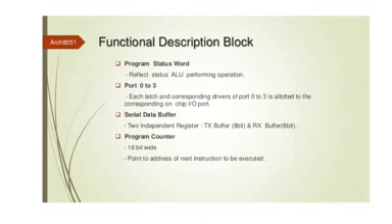Next, the serial data buffer: 2 independent registers, one for the transmitter and one for the receiver. Whenever you receive data from some other place to our 8051, the received information is in the receiver buffer. Whenever you transmit, the transmit data will be stored in the transmitter buffer.